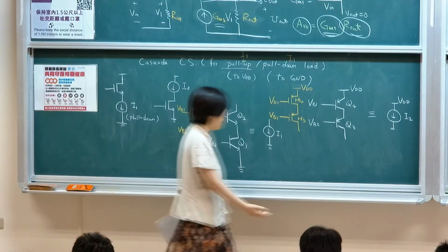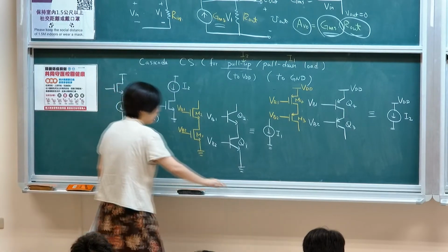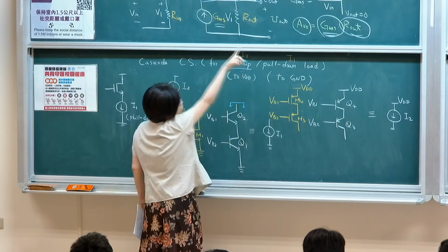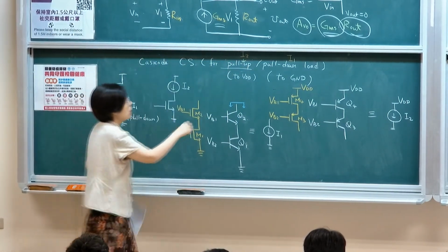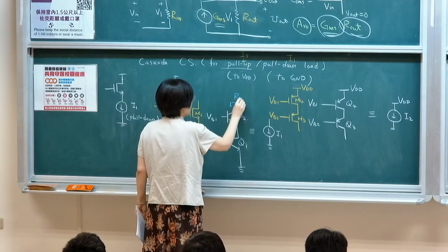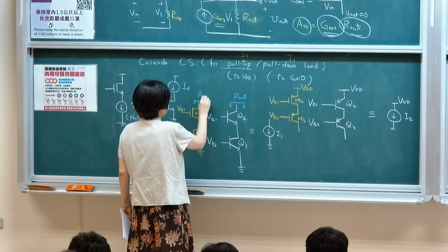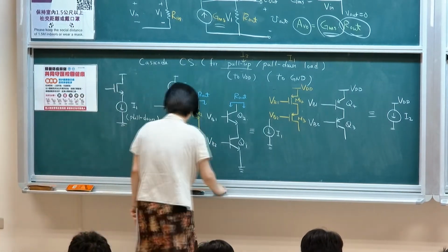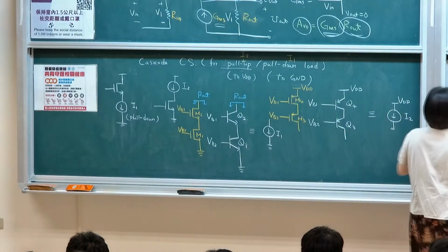So let's look at how your output resistance changes. One of the key performance factors is this: you want to press it down. You want to make sure that the slope actually decreases. So the key performance factor is actually R out here. Right? You want to find out what the RL is for these two cases. So let's look at a MOSFET version first because it's easier.